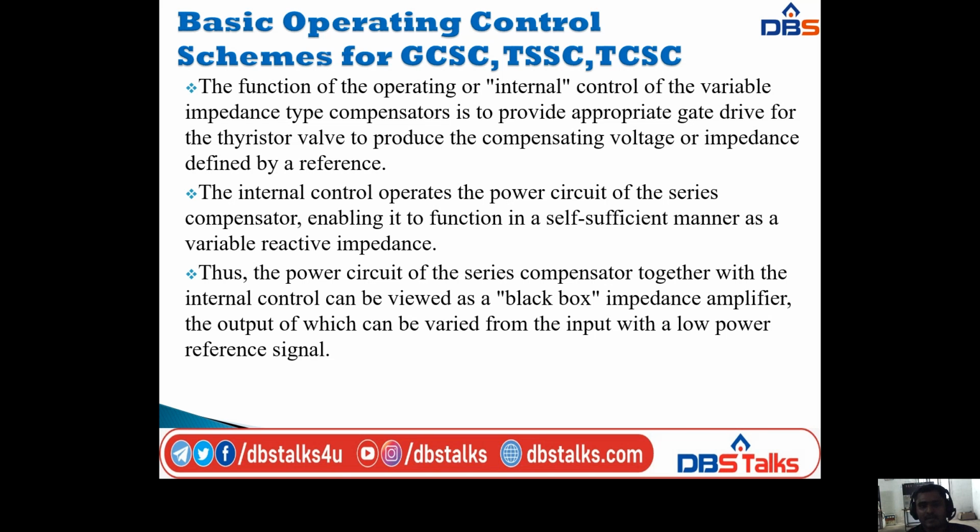So the function of the operating or internal control of the variable impedance compensators, that is GCSC, TSSC and TCSC, is to provide appropriate gate drive for the thyristor valve to produce the compensating voltage or impedance defined by a reference. So the internal control operates the power circuit of the series compensator, enabling it to function in a self-sufficient manner as a variable reactive impedance.